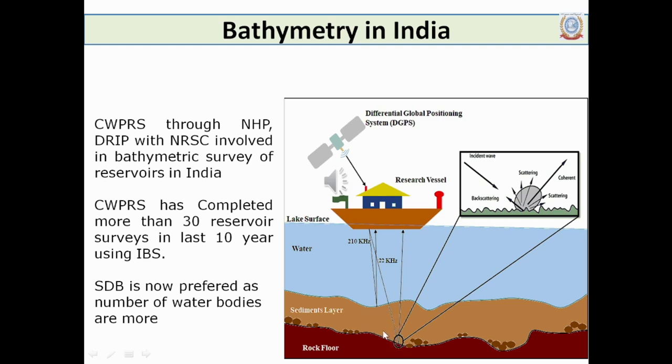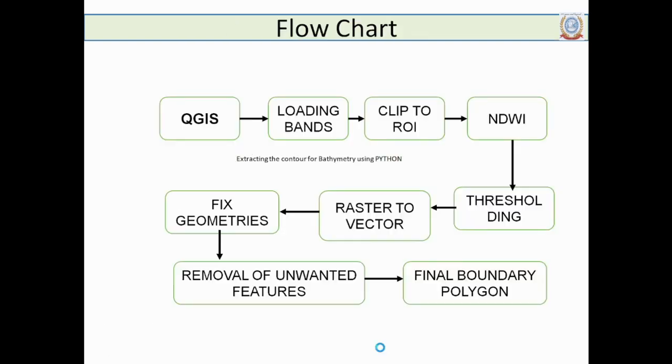With the difference you are able to get the sediment at a point, with the GPS position tagged at every instant. At the point of interface you get a lot of interaction, so the mathematics and modeling taking place in the echo sounder concern the strength and quality of the signal being acquired. If you vary the frequency further down, you have an opportunity to go further beyond this, which we already covered in session 1 as subbottom profiling techniques.